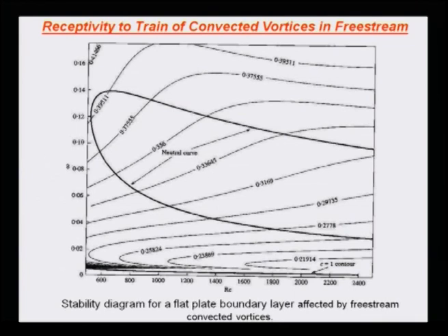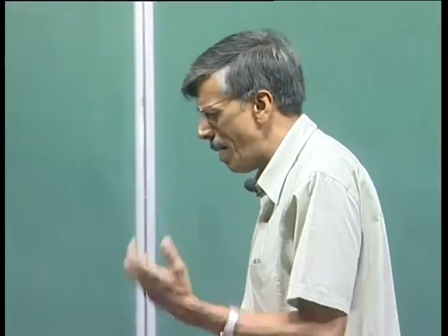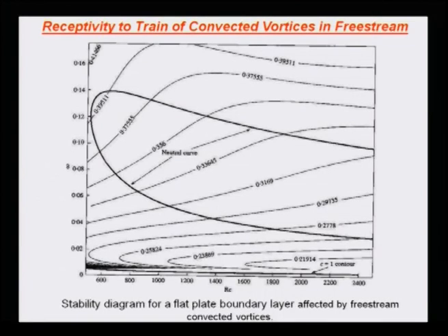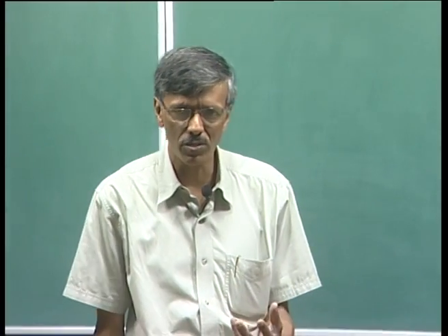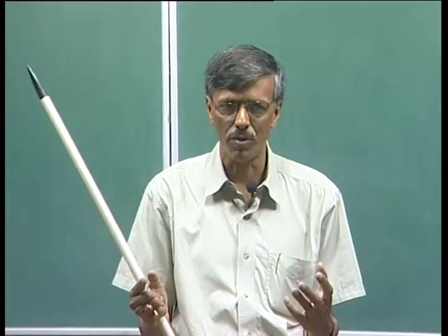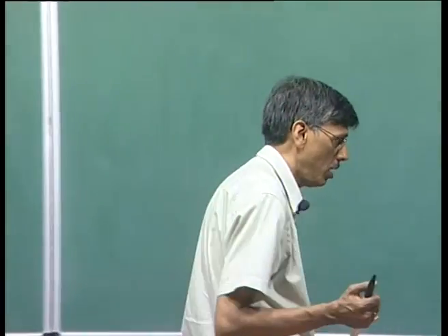of creating instability by viscous vortices moving in the free stream is a very, very potent one. Since this creates wave packets and not a single wave, we went with the crowd and called it a bypass mode, but the constituents are still the Tollmien-Schlichting waves. So we are getting a wave packet constituting many, many TS waves. That is what we should be looking at, and we go ahead with the calculation.